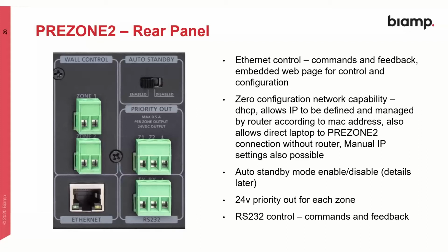And this is very common because users want to have a level control that they can adjust within the zone, and a very simple level control. And that's fine, that's good. We very much support the use of those volume controls. But it does cause a problem because when the volume control is turned all of the way down, if you make an emergency announcement, you will not hear the emergency message.